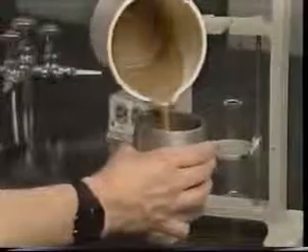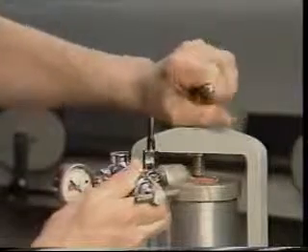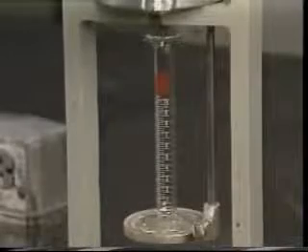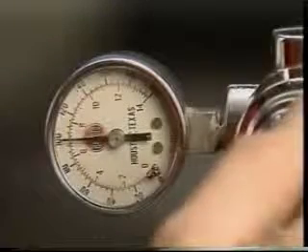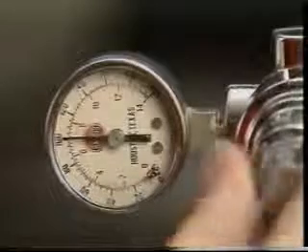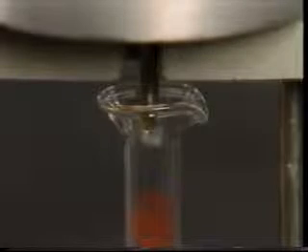The rubber gasket in the top cap is checked, and the cell is filled to within 1 inch of the top with a mud sample. The top cap is placed on the filter cell, and the cell body is secured into the frame. Next, the graduated cylinder is placed beneath the filtrate tube. A pressure of 100 psi is applied to the cell and the timer immediately started. The test is continued for 30 minutes. After this time, the amount of filtrate is recorded to the nearest 0.1 cubic centimeter. This filtrate is set aside for other tests and the gas pressure removed.